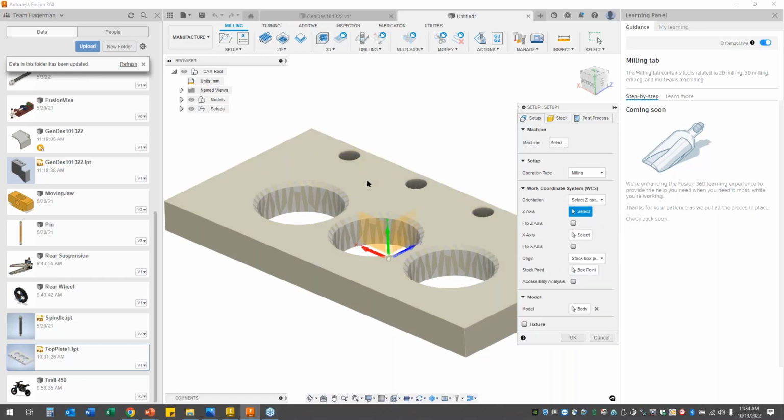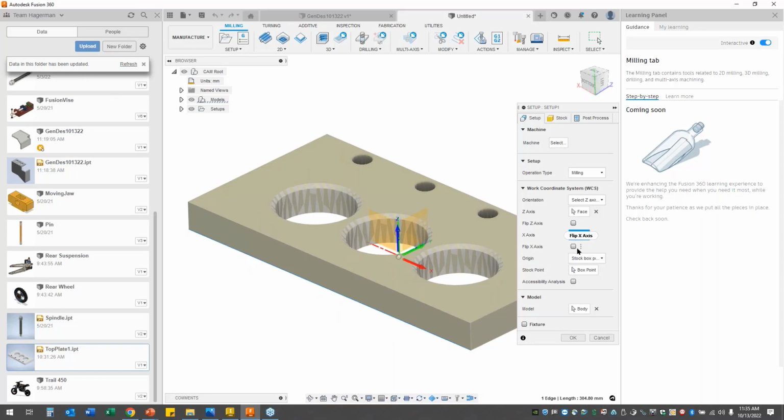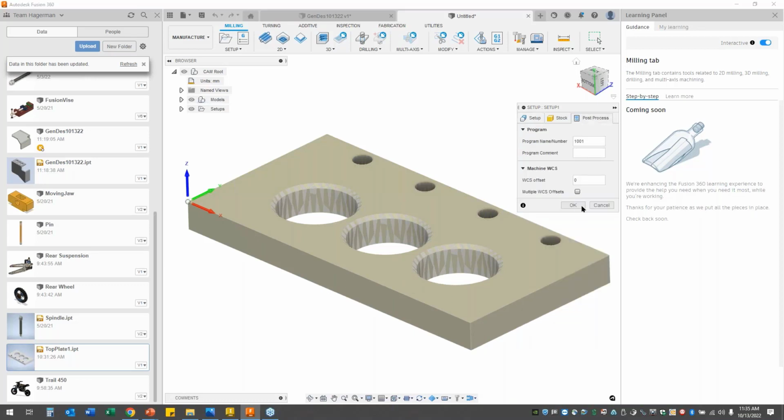So if I want to have my Z-axis plane, say, set right here, I can do so, and then I can come in and set, say, the X-axis. I can change my order. I select a point for the origin, and all I have to do is pick on the little triad and slide it over. Nothing real hard. If you guys have worked with the machining setup, you've seen these before, and you can even set some things for your post processor.